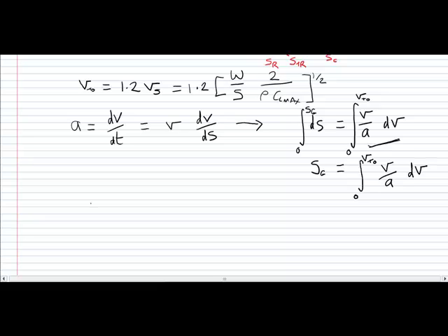So we can compute that quite easily, starting with Newton's second law. So we just say that F is equal to ma. And obviously this is the net force is equal to the mass of the aircraft times acceleration, and the net force for the aircraft rolling along the runway is thrust, which you should have a value for. Your engine specialist should be delivering you your thrust value, which may or may not be a function of speed, depending on what engine type you're going for, minus the drag of the aircraft, which will be dependent on the drag coefficient that your aerodynamicist has been working on for the last couple of weeks.